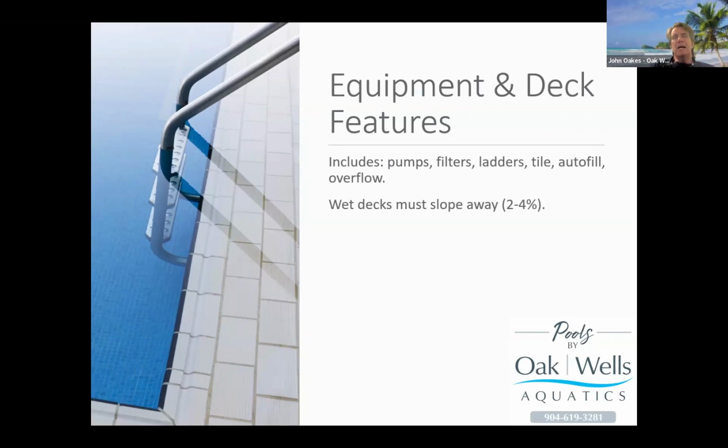I mentioned earlier the tile when we were looking at the residential pool that had tile spotters. If you look at this particular photograph, the black tile that's right on the edge of the gutter is what we call the waterline tile. There's tile very similar to that on the edge of all the steps and all the benches. That tile has to be non-skid. It used to only have to be non-skid over stairs. Now it has to be non-skid any place that it's installed where the area adjacent to it can be used as a step. So this gutter can certainly be used as a step. There's only about a quarter of an inch of water in it out by the edge.